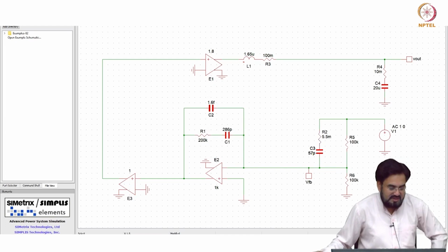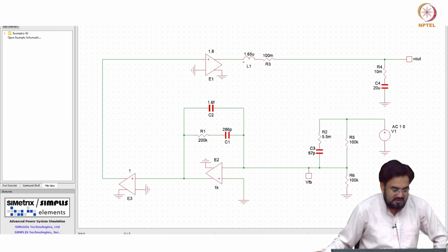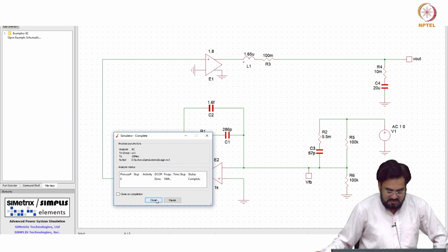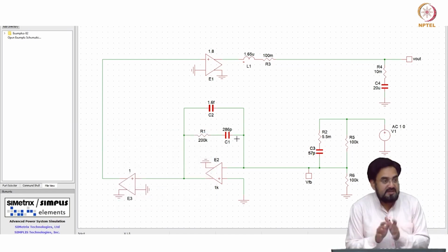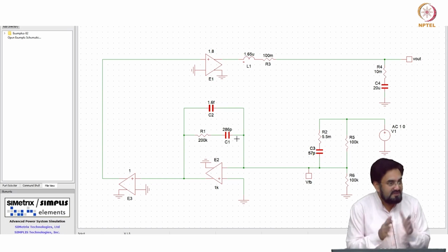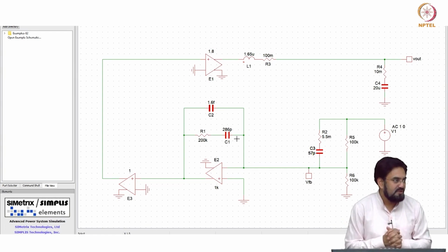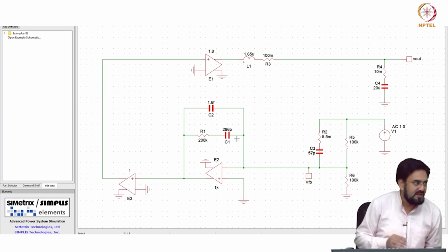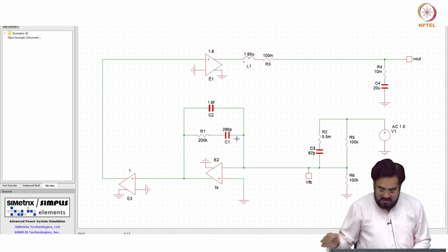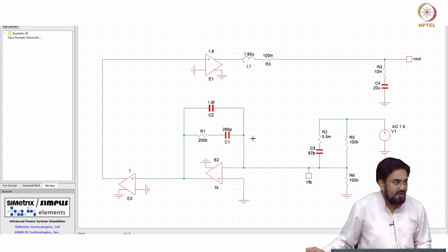So, you guys remember, one thing you need to remember, it should not affect your loop gain, these poles, that is why we are keeping them outside UGB. It may have some effect on your phase margin, because even if you keep it 5 times away, tan inverse of whatever you get from that pole divided by omega UGB, there will be some contribution because of that, maybe 5 degrees or 10 degrees whatever. So, these two poles may cause a drop of maybe 10 degrees or so in the phase margin. So, that is how you decide.